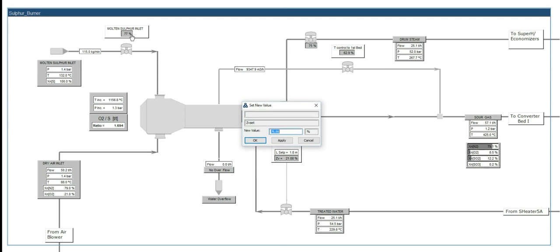So let's go to 85% opening. So we go to 127 kilos per minute. We see that our temperature is rising. We have increased the steam production. Our control valve for the first bed is now closing the bypass valve, trying to maintain the temperature at 425 degrees, which is the set point to enter the bed of the